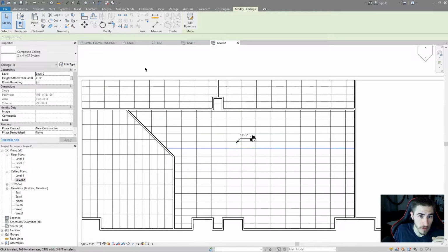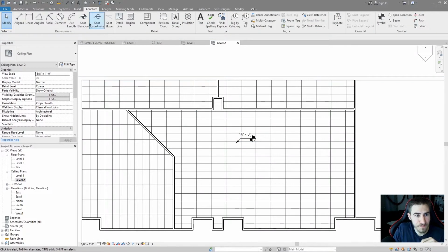Again, if you're using relative to the project, it's going to start from the base point, which is probably 0 or 100 or wherever you've started it, and it's just going to count straight up. That's nice if you need to know that distance. I don't necessarily need that if you're just doing one ceiling. If you need like an exterior element that's sitting out on a column, you need the height of that, and that's probably where you might begin to use that.